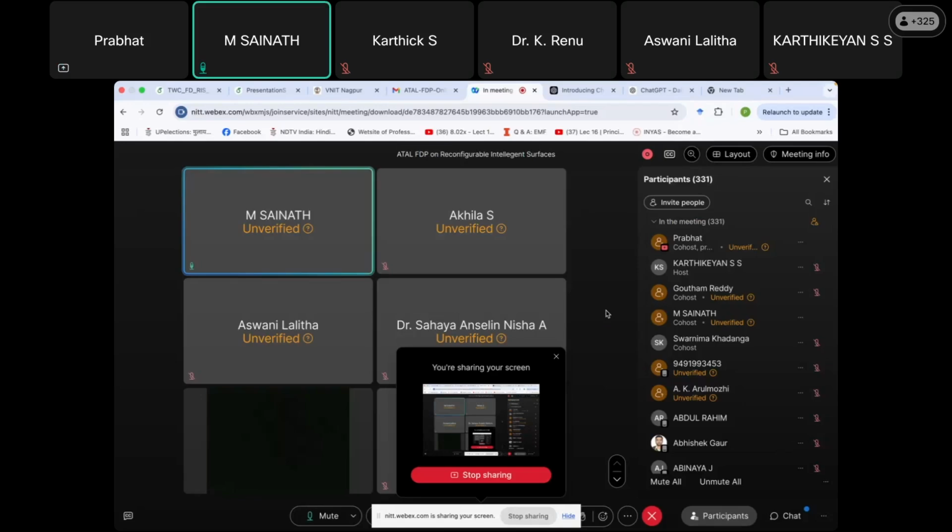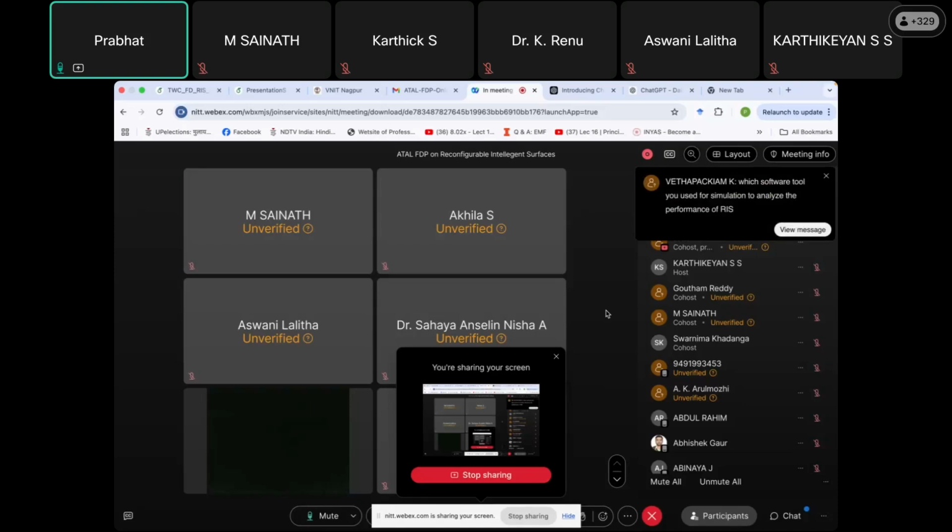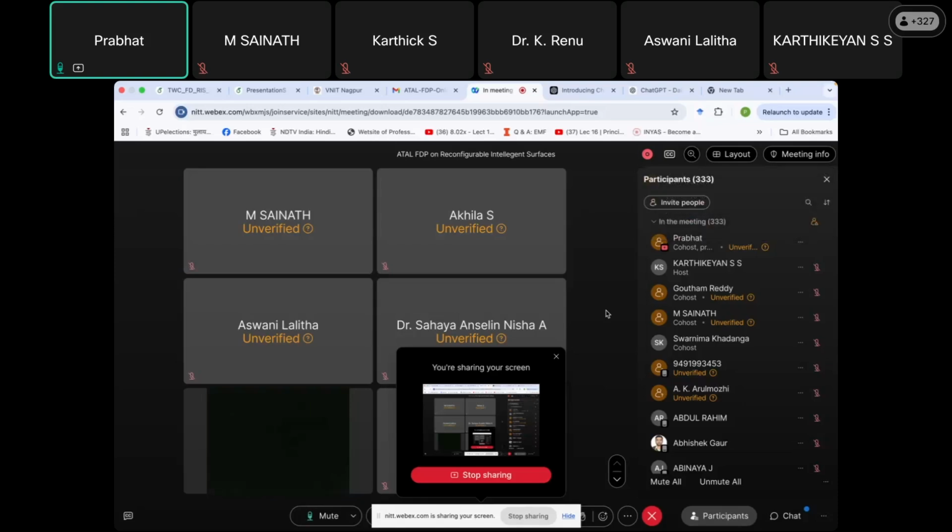Okay, sir. Moving to the next question. The RIS placement, how does it impact the interference and also the final result? Yes, it makes a lot of impact. Where are you placing the RIS? As far as whatever work we have done, and also affirming it from the available literature, RISs are generally advised to be placed either close to the transmitter or close to the receiver, right? But when you are changing the location of RIS, certainly its impact is going to be there on the system performance, because when you are changing the location of RIS, the channels are going to change, and estimation of those channels would be required, and then you have to modify your phase response of the RIS for the changed or new channels.